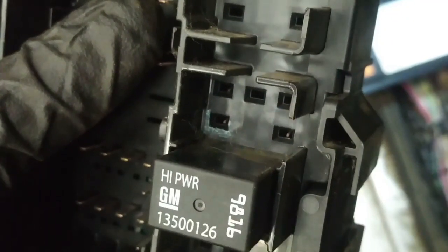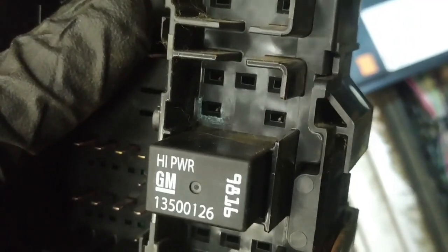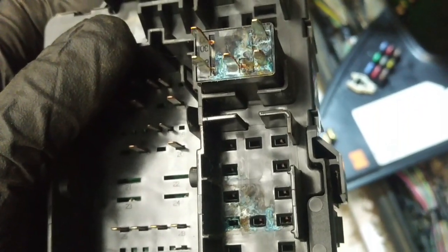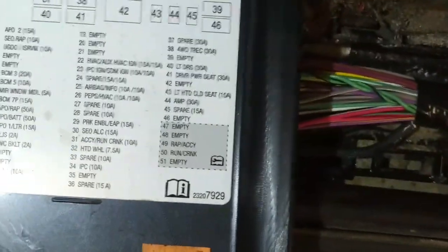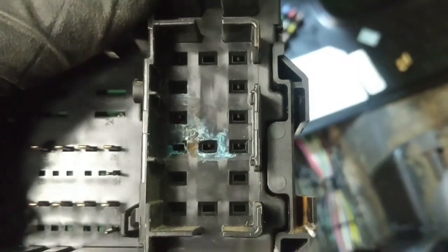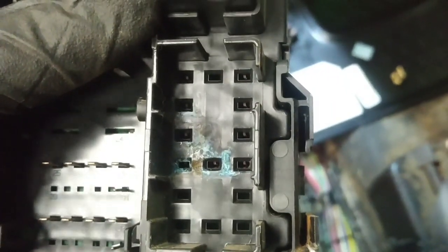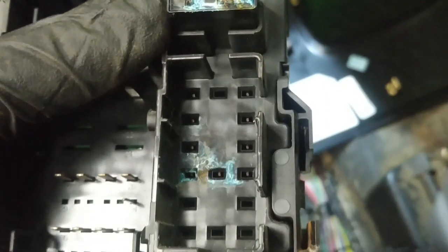So I got the fuse panel out. Although the rest of the fuse panel looks clean, that one terminal for some reason is oxidized. I'll pull this other relay out and have a look at it. Well, isn't that special? So you tell me how moisture gets in the back of this. Now that second relay, the one I just took out here that you can see the bottom of it, would be the run crank relay. Oh, lovely. Well, we'll try and clean that up. Hopefully that's the cause of the problem. It's not doing it now, so it's difficult to tell, but definitely that's a concern.